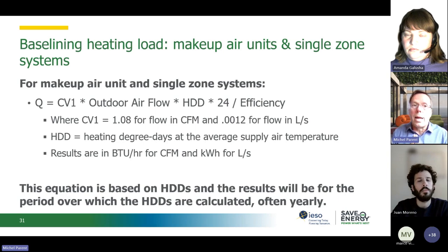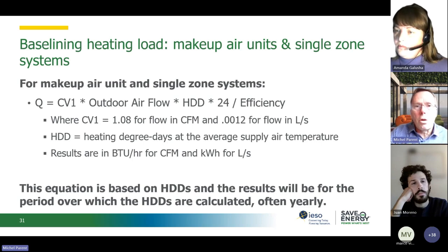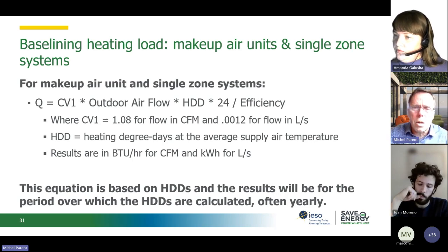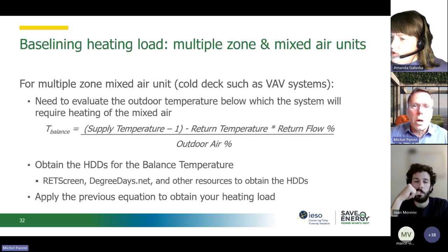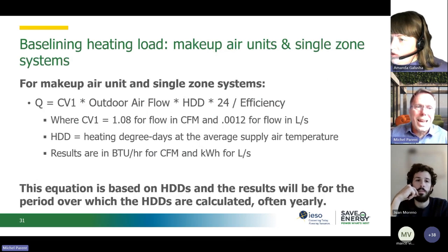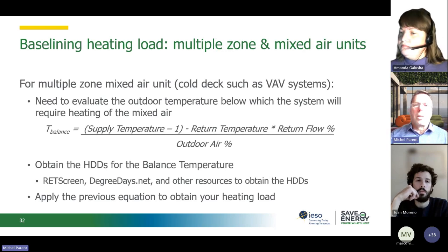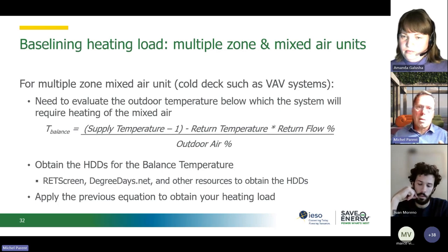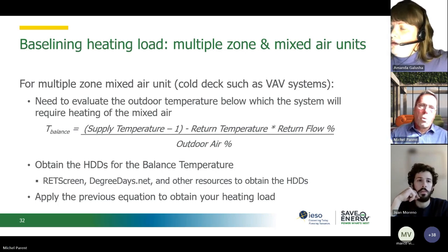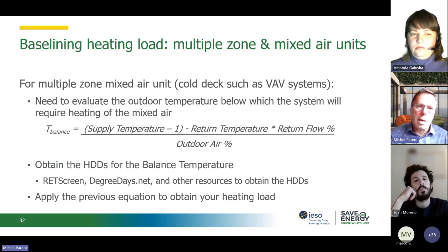Now, if you've got a VAV system, anything that is multi-zone cold deck, so a reheat system, a VAV system, you can use the same formula with a very important distinction. The temperature where you're going to calculate your heating degree days has to be calculated based on this equation. And again, apologies for the math here, because what happens with a cold deck system that has mixed air is that your supply temperature will be your limiting factor in determining how much you need to heat that outside air.